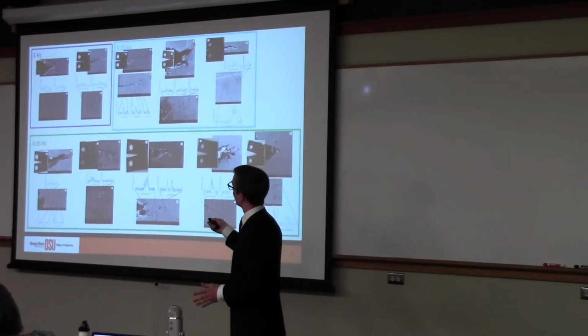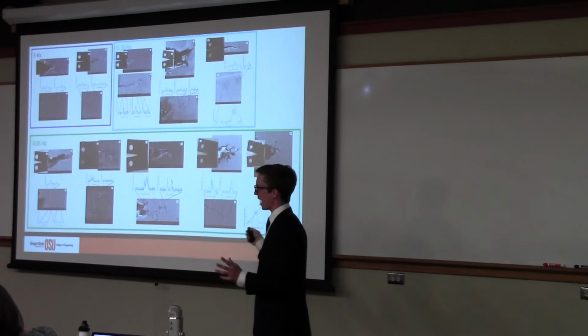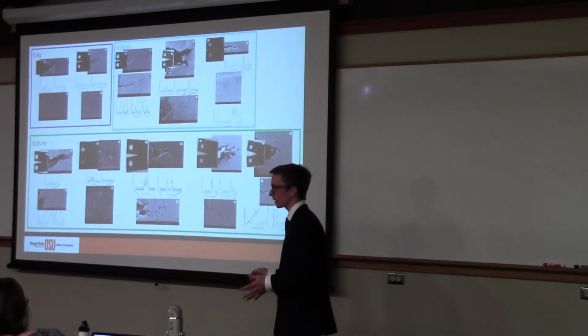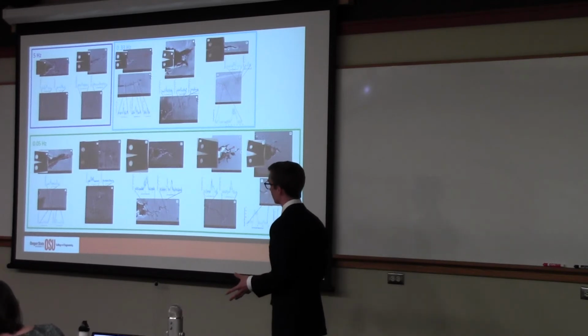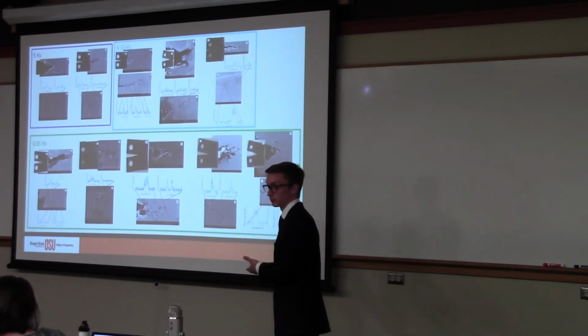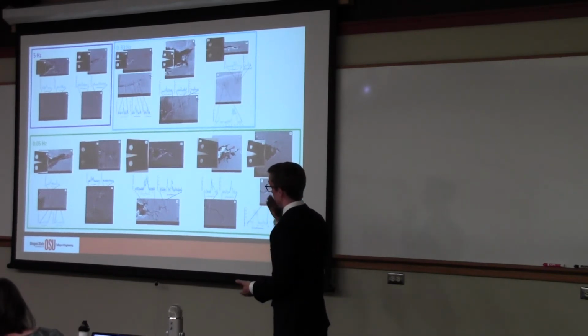What we're trying to do here is measure oxygen at the crack tip, okay, and specifically oxides that are forming at the crack tip, and see if that has some impact on the crack growth rates, or at least see the relative concentrations of oxygen in all these crack tips. And what do we see?